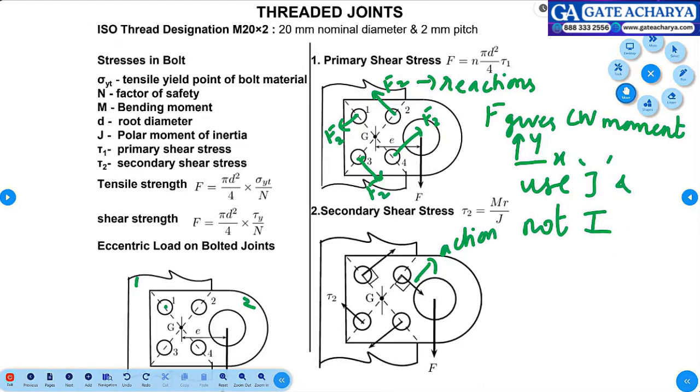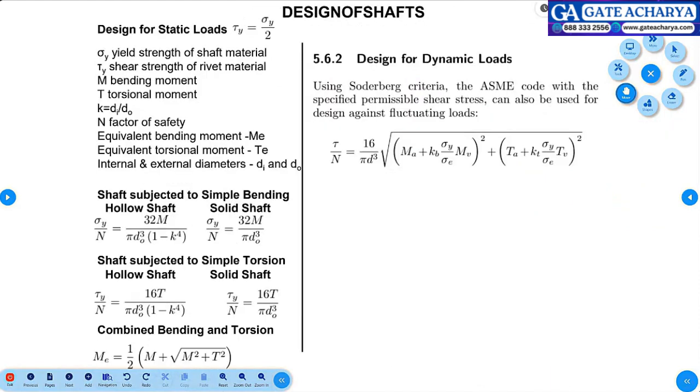Okay, here we were. Design of shafts. You know what is a shaft? It's a machine element that is meant for transmitting power. Power means torque will be present, speed will be present, both. Torque and speed make power, from one shaft to the other, input to the output. So whenever you use the word shaft, it is primarily a function of torsion because it's rotating like this, right? So it will be subjected to shear stress.